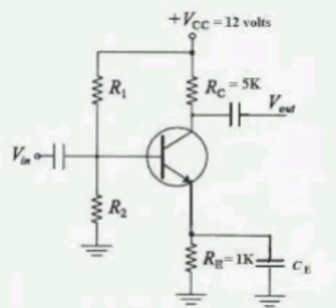FF1 is having an active high asynchronous clear terminal. If clear input of flip-flop 1 is 1, irrespective of W input, flip-flop output is 0. If clear input of flip-flop 1 is 0, after applying W input, FF1 will follow the truth table of JK flip-flop. Case 1, clear 0. FF2 output is 0, so FF1 J1 equal to 0 and K1 equal to 1. After applying W input, flip-flop output is 0.